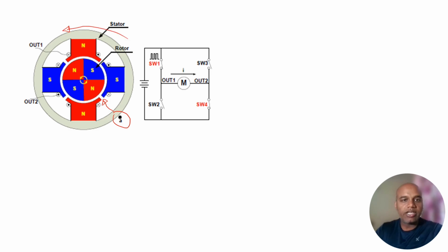So the rotor running direction is the anti-clockwise direction. And from when the Hall sensor output is high, switch 1 and switch 4 will get closed, and the modulated pulse will energize my stator winding through switch 1 and switch 4.